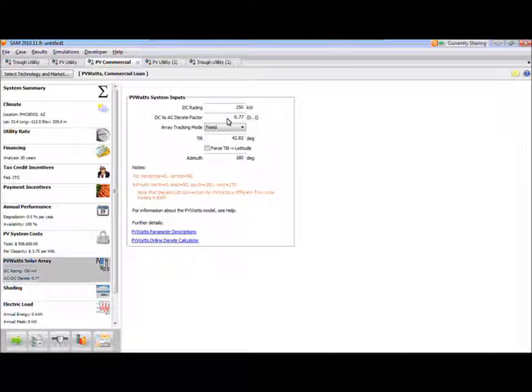And for the PV watts model, there is a temperature correction algorithm. The model applies this temperature correction factor based on the wind speed and ambient temperature data from the weather file. So the hourly efficiency isn't completely constant. There is a temperature adjustment.